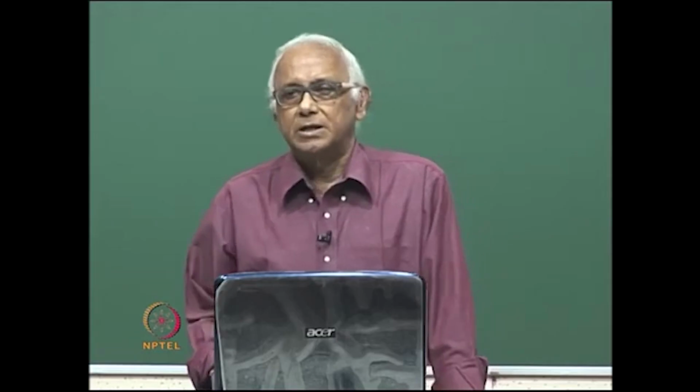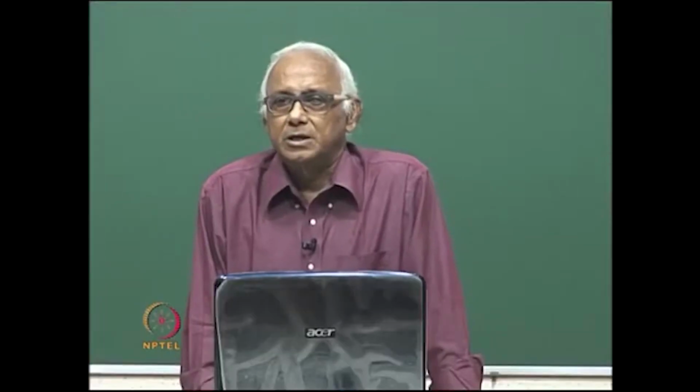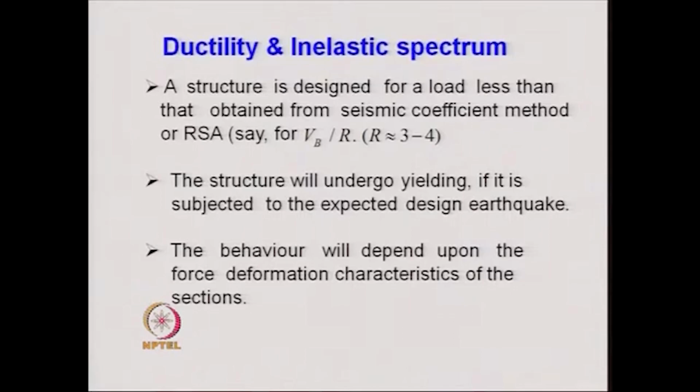For finding out the ductility demand for each element, one has to carry out a nonlinear dynamic analysis, or nonlinear seismic analysis, of the structure, find out the maximum displacements or deformations that take place in individual members, divide them by the yield deformation or yield displacement, and find out the ductility for each member. So, we want to see now how this ductility is obtained for a structure element-wise, as well as for a single degree of freedom system, or what we call the overall ductility of the structure.